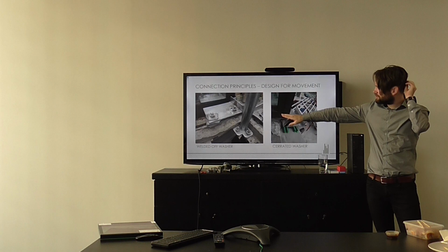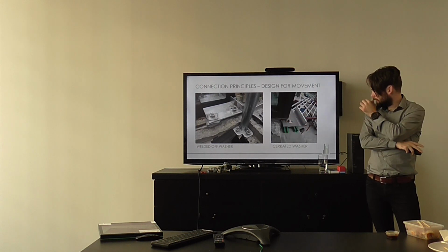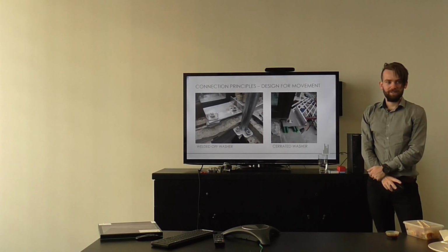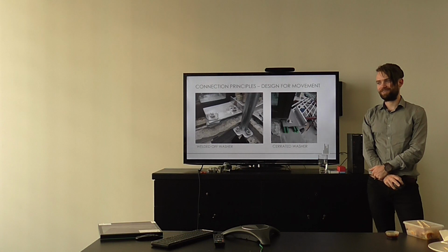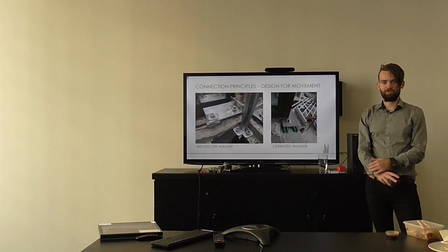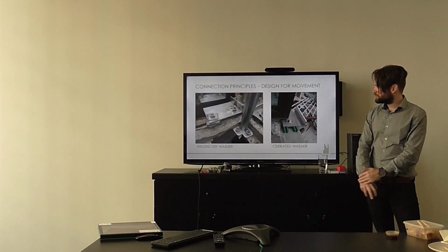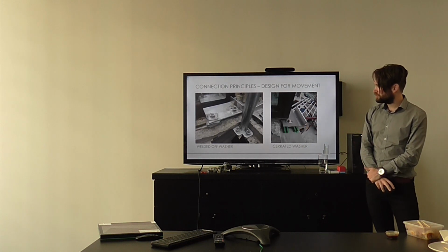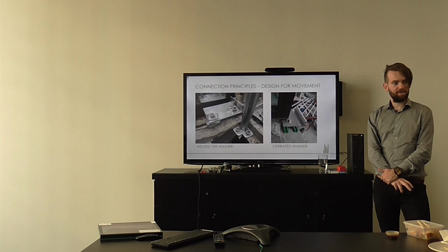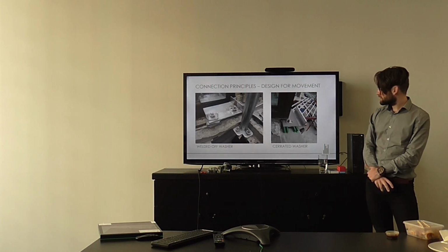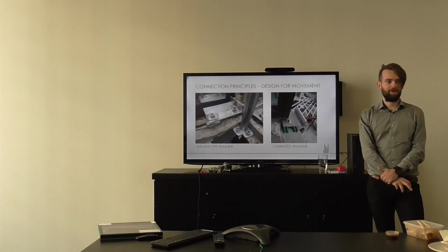One of the big differences between these two drawings is packing. Now, as I touched on before, packing is not our favourite thing in the world because it can lead to some problems with bending of our bolts if there's a lot of it. So the diagram on the left there is quite good. They've got some nice solid steel packers in there. On the right here, maybe not so much, but if that was to be grouted under, it may be sufficient.